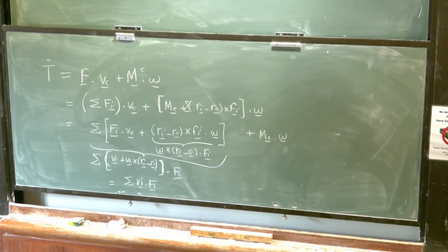Okay, so the conservation of energy, all the conservative forces, conservative moments apply in the same way they did before for particles and systems of particles. So for example, if I go through Problem 2, is the energy of the plate conserved during its motion? Problem 2, a uniform rectangular plate is released from rest in the position shown. Determine the maximum angular velocity omega during the ensuing motion. Friction at the pivot is negligible. Is the energy of the plate conserved during its motion?